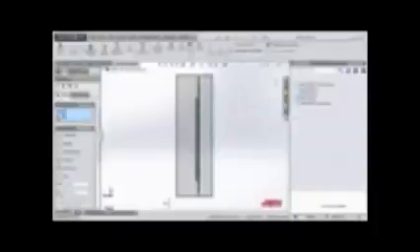The back of the board is now fixed to the back surface of the enclosure because the default for mates is coincident. Note the two surfaces that were selected under mate selections above. If I click on the measure button, I can then define an offset, let's say 13 millimeters. The board is now 13 millimeters from the back surface of the enclosure and will not move more than 13 millimeters off of that surface. We'll click the checkbox to save the mates.